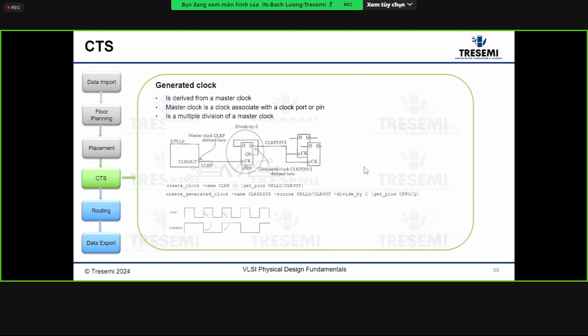Okay. So the advantage of having the generated clock is that there's no new clock domain. You just use the existing clock and create a new divided by 2 clock. So it simplifies things in terms of building clock trees and also makes your design much easier. So you'll see in most designs a generated clock and virtual clock. So I felt that's important, so I added these 2 slides as part of today's lesson.